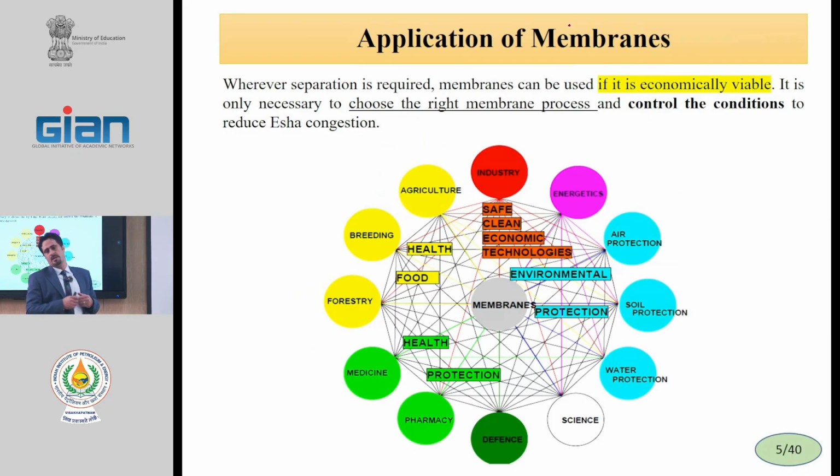Therefore, the membrane scientists first check the economical viability, and the second is fouling problem. Maybe one process can be instituted with the membrane, but the membrane will be destroyed during 1 week. Membrane can separate, but have not durability, chemical durability, solvent durability, thermal durability. Check these conditions. If the membrane can be used for a long time, membrane can be used instead of a traditional process.